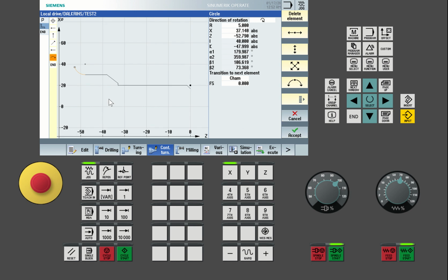Then we go to another contour. I want to add another contour here. Change now, you can change this one to anti-clockwise. Put the value as 2, for example. Then X here, we can put the value for X as 40.